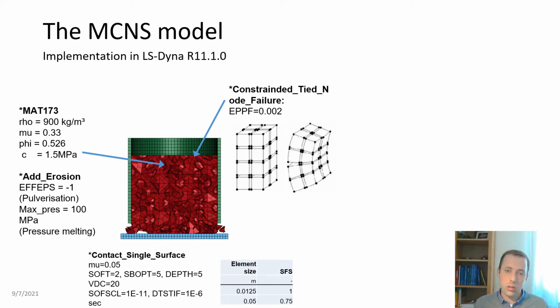And so I think the element type or the node splitting approach will represent the physical behavior of ice much more accurately, and this is the reason why we are using this approach. During node splitting, in case of failure, only the nodes are detached from the neighbor elements and the mass and volume is preserved.